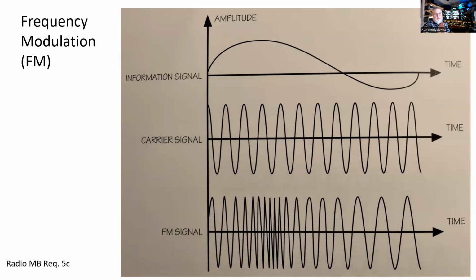If it's very low, the modulation rate is very low. If it's very high, the modulation rate is very high. Again, the amount of deviation is volume. The rate of deviation is the frequency of the modulating signal. So again, we can either turn a carrier on and off in Morse code, we can vary the amplitude of a carrier, or we can vary its frequency. Those are the 3 main methods that we use to put information on a carrier when we send it from a transmitter to a receiver. When it gets to the receiver, it strips away the carrier and keeps the variation.